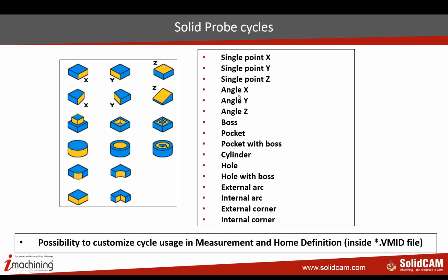Not only the options inside the cycle. If the cycle exists in a specific controller, maybe it doesn't have all the options. SolidCAM makes a collection of all possible options in the most used controllers, and for each controller we define the options in the post-processor and what the cycle can do, and depending on this we build the post-processor.